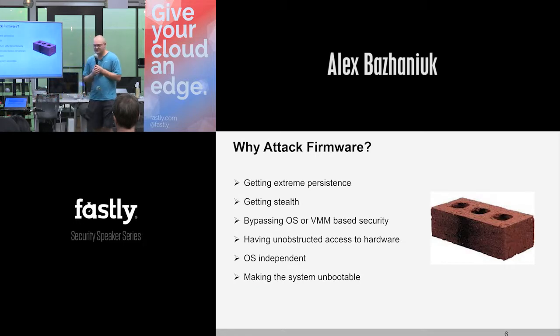So why are firmware attacks really important? First of all, because if from the kernel you can compromise the firmware, you can make a really persistent implant, meaning some malicious code can be injected in the software which will survive after reboot, after reinstallation of the operating system, and even if you replace the hard drive, it can still survive because it will infect the firmware, and the firmware itself lives in a SPI chip, which is basically a special controller which is necessary to run the boot flow in a system. And pretty much all of the x86 systems have the SPI controller with the SPI memory and the BIOS there.